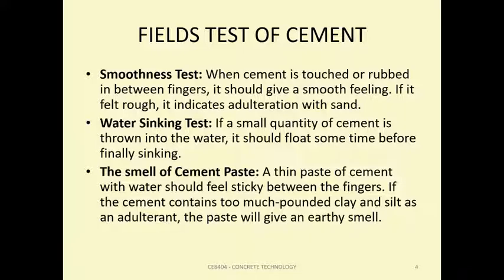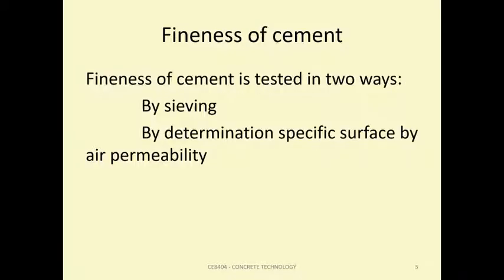The next one is the smell of the cement paste. A thin paste of cement with water should always be sticky between our fingers. If the cement contains too much clay or silt, it is an adulteration, and the paste will have an earthy smell. The next one is laboratory tests.